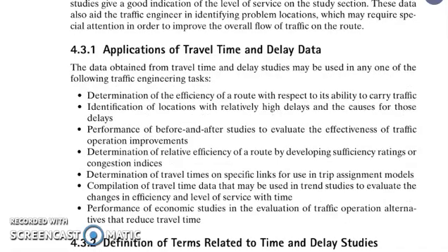So what are the applications of the data gathered from travel time and delay studies? The data gathered from our travel time and delay study can be used for the following traffic engineering tasks: determination of the efficiency of the route with respect to its ability to carry traffic, identification of the locations with relatively high delays and causes for those delays, performance of before and after studies to evaluate effectiveness of traffic operation improvements,